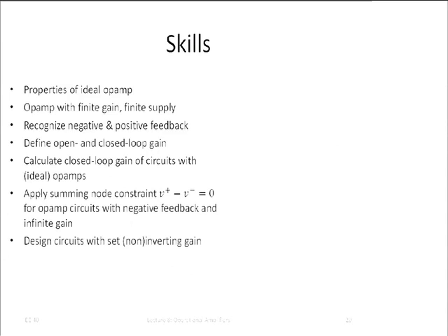So your question: the current into the input of an ideal op-amp is 0, right? You need to know that. The gain is infinite, okay? And the output voltage is simply the difference of the input voltages multiplied by the gain. Then occasionally we actually make the gain of an operational amplifier not infinite, right?